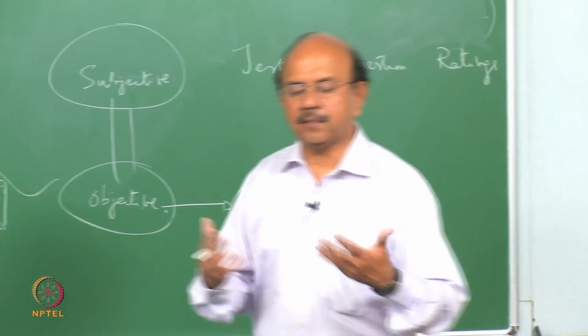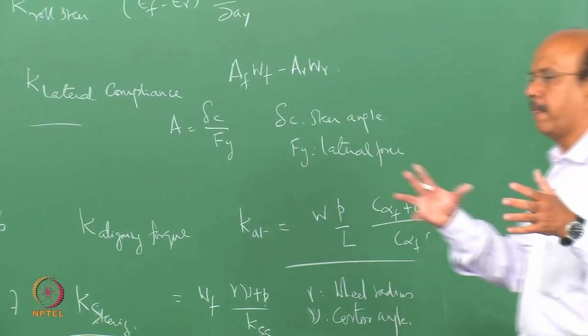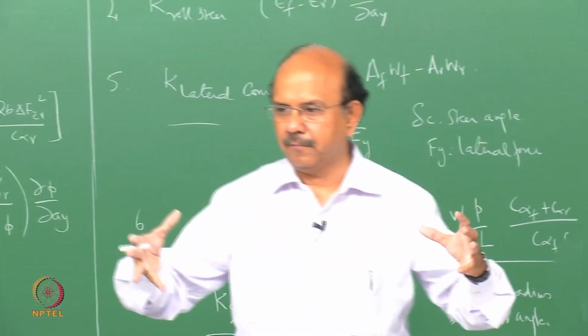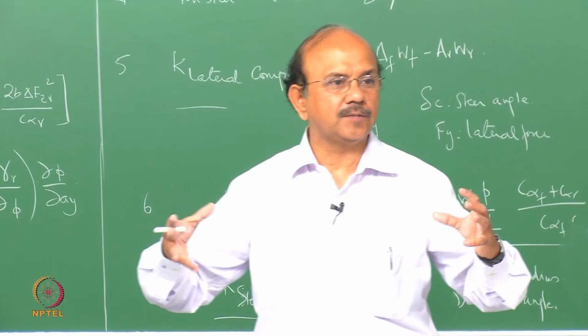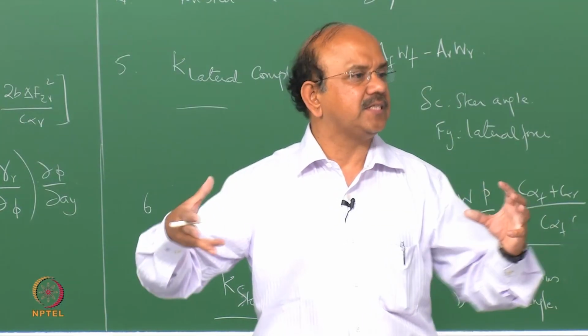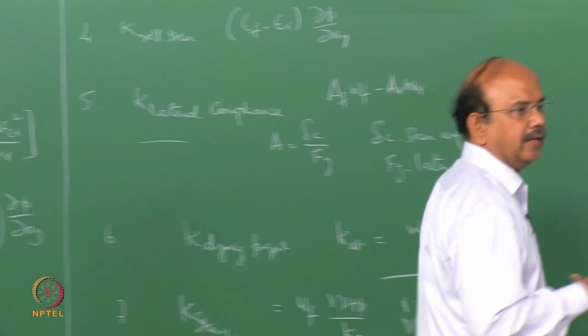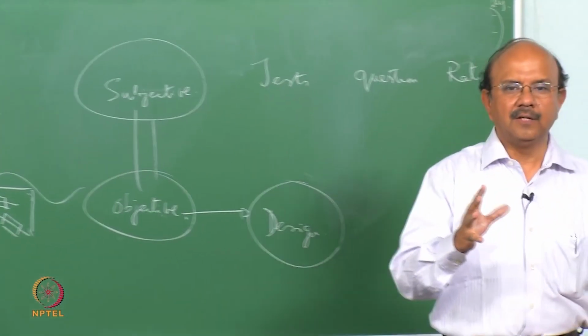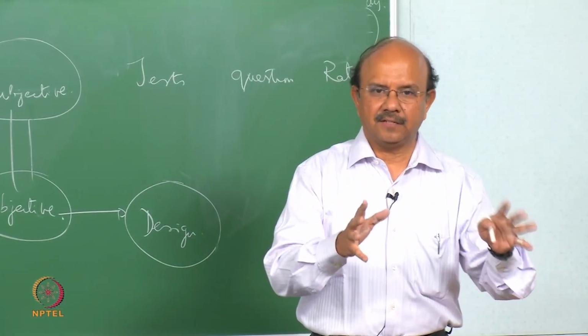Sometimes, due to so many reasons, the left and the right torque may not be the same, and there can be a difference because of which there can be a steer. There can be an unbalance in the torque that is given to the front wheel, and because of that there can be a steer.